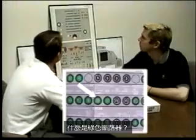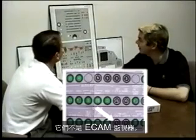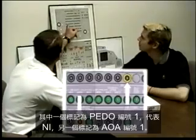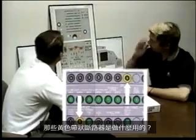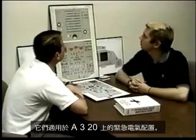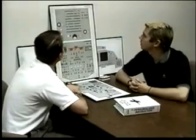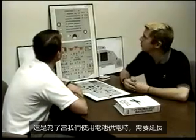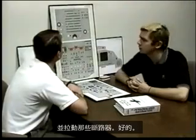What are green circuit breakers? Those are ECAM monitored. What about the black ones? They are non-ECAM monitored. I notice there's 2 yellow bands. One's labeled PIDO number 1 for the antis and AOA number 1. What are those yellow banded circuit breakers for? They are for the emergency electrical configuration on the A320, and it's for if we're on battery power and we need to extend the battery life. If we're in VMC and not concerned about icing, we can go and pull those circuit breakers.